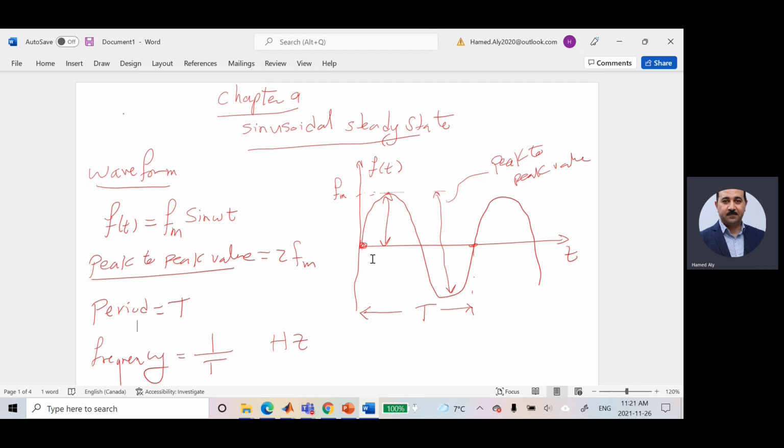Why? Because for the capacitor in phasor domain, the voltage across the capacitor is equal to the current I multiplied by negative j, which is a complex number, times something we will talk about next class. It is called X, the reactance. And we will not say V is equal to 1 over C integral of I dt plus the initial voltage.